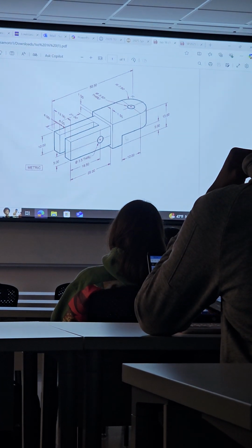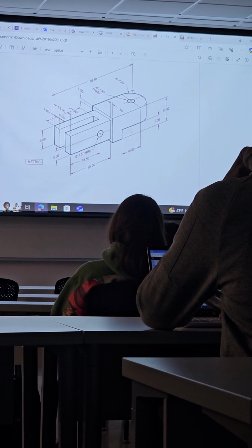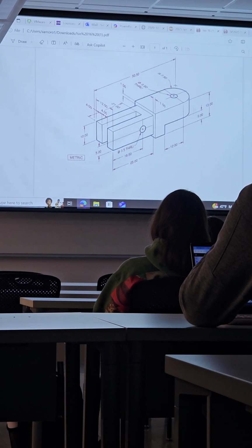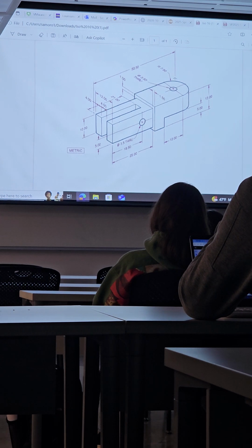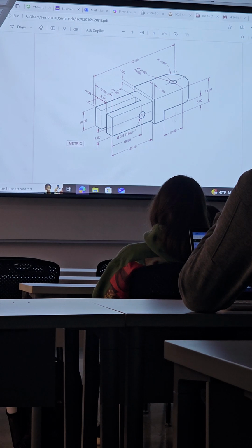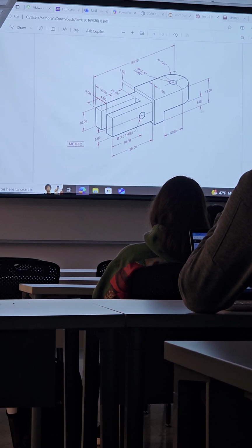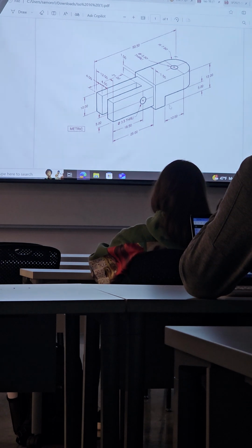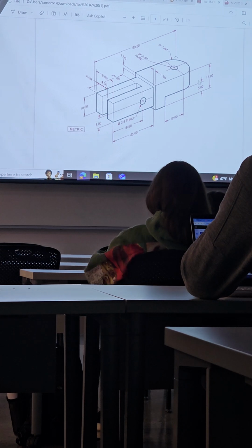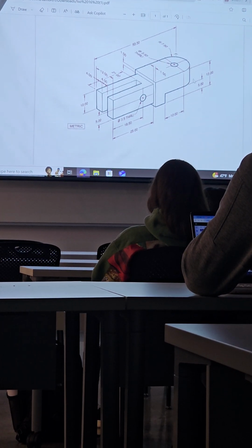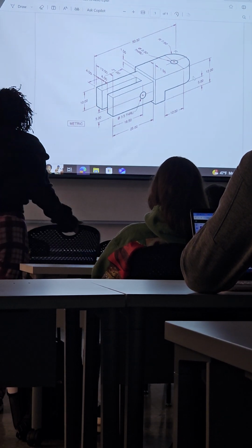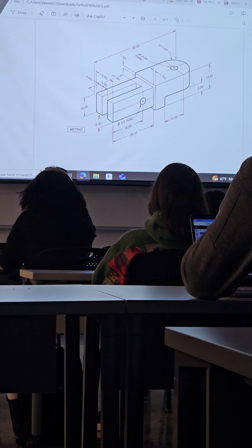So the next position I'm interested in is this edge, which is 13 minus 5 units from the top. So here's an interesting aspect of dimensioning that you should keep in mind. The height from here to the bottom is marked as 13 units. And they've given me the height from the bottom to this other edge as only being 5 units. That means the difference is 8 units. But they didn't tell me directly the 8 units. If they had, that would have been an instance of double dimensioning, because the information is already there. You just have to do a subtraction problem.